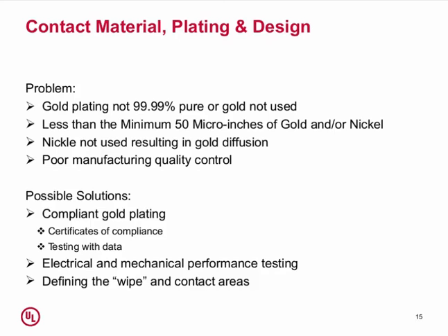Thinner gold plating looks great, wears faster. Without gold connections, you have corrosion issues. Sometimes nickel is not used. If you don't have a nickel substrate between the gold and the metal on the contacts, over time the gold will actually diffuse into the metal and you'll lose your plating. And again, that can result in corrosion over time and bad transmission connections.